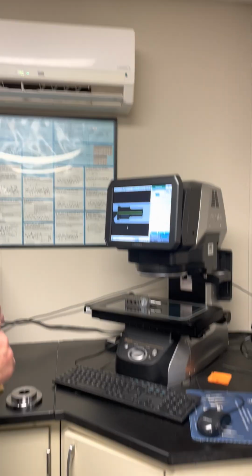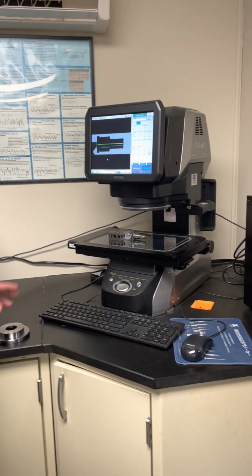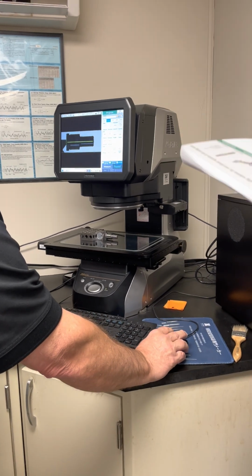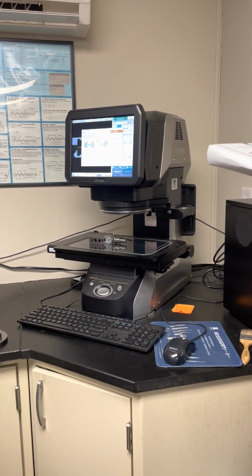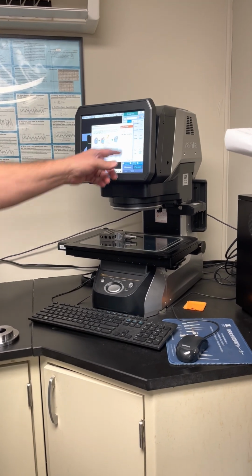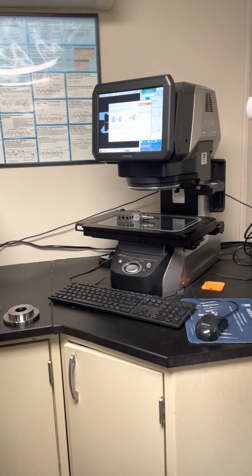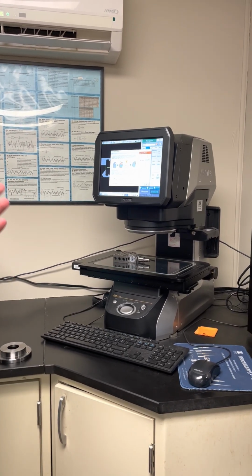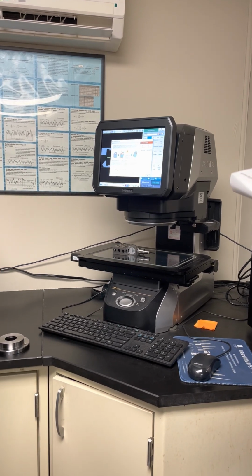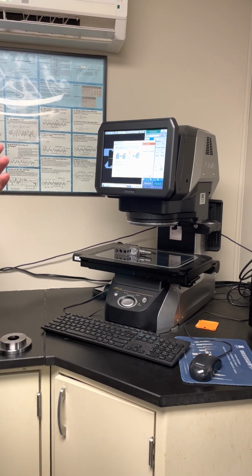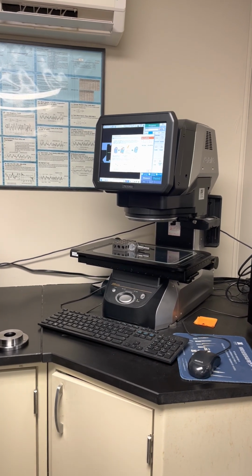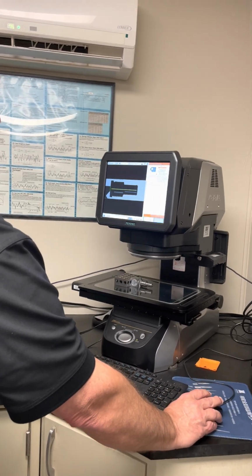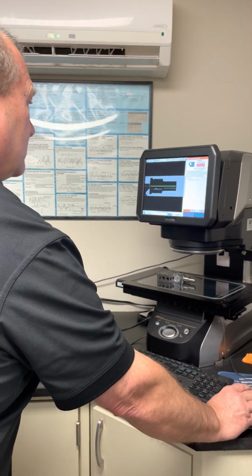Now what I'd like to do is throw in a coordinate system. You're going to find that down here, coordinates. You're either going to use two lines or a line and a point. In this particular case, we're going to use two lines to create our data structure. You don't have to worry if the lines are not perfectly perpendicular to each other, because it's going to take the first line as your X, the second line, it's going to create that intersection, and then it's going to draw a perpendicular off of that intersection. So for now, I'm going to say two lines, and there's my X, and there's my Y.